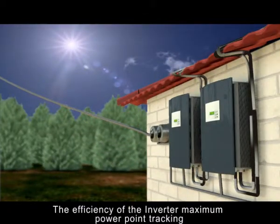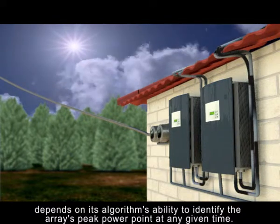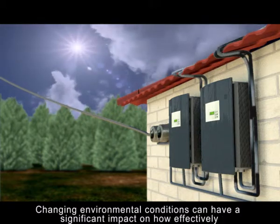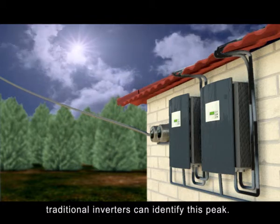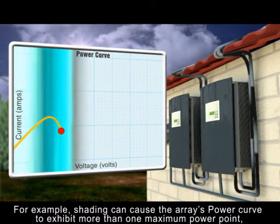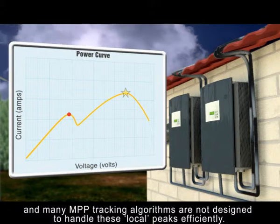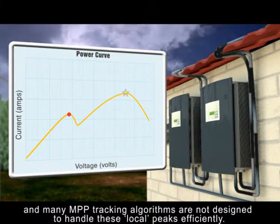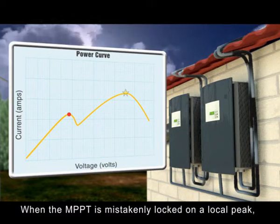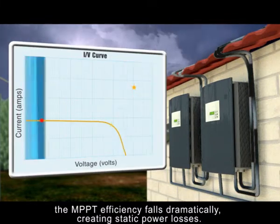The efficiency of the inverter maximum power point tracking depends on its algorithm's ability to identify the array's peak power point at any given time. Changing environmental conditions can have a significant impact on how effectively traditional inverters can identify this peak. For example, shading can cause the array's power curve to exhibit more than one maximum power point, and many MPP tracking algorithms are not designed to handle these local peaks efficiently. When the MPPT is mistakenly locked on a local peak, the MPPT efficiency falls dramatically, creating static power losses.